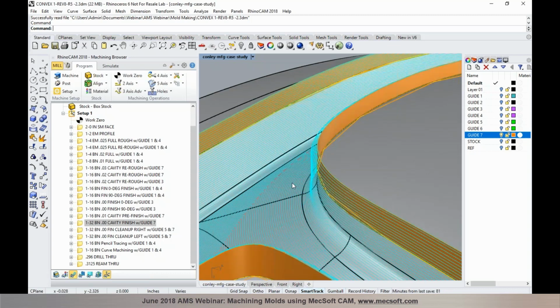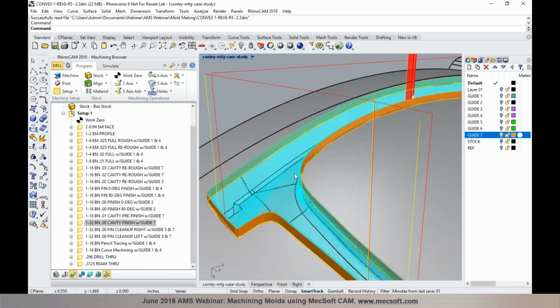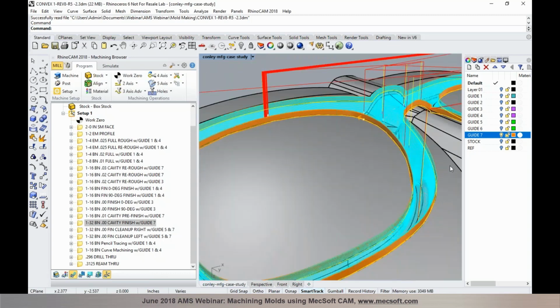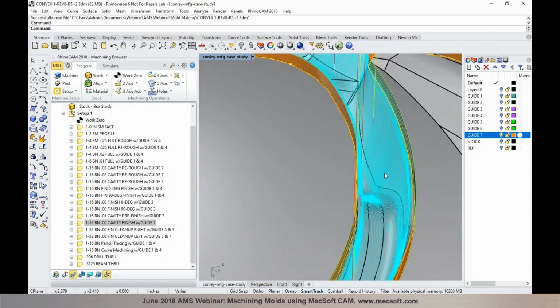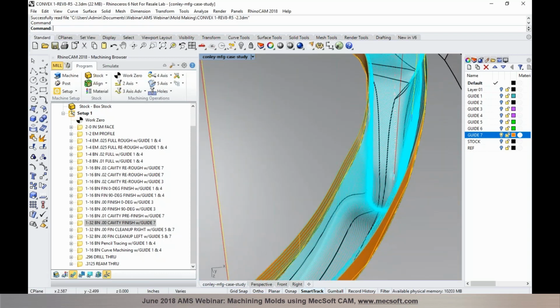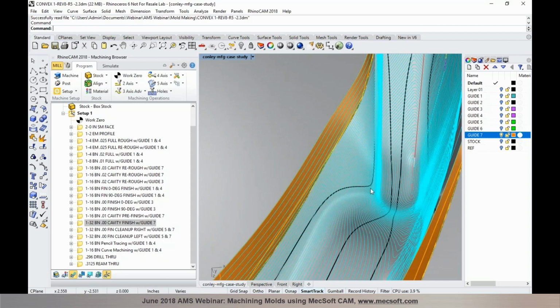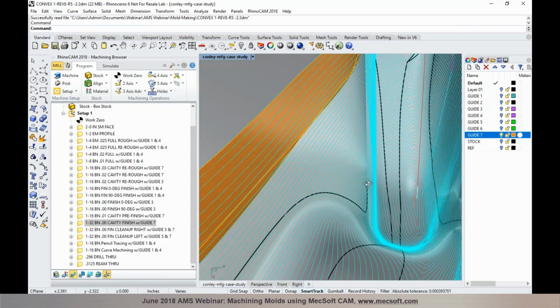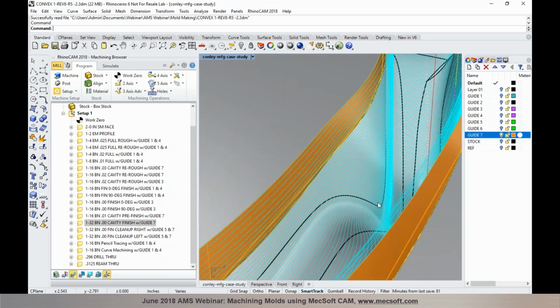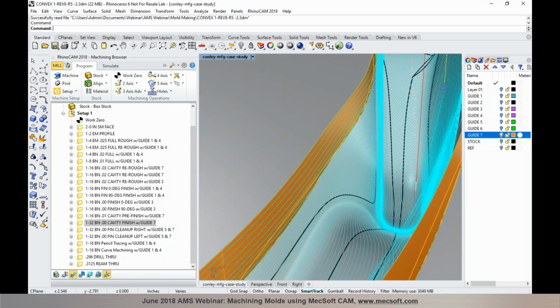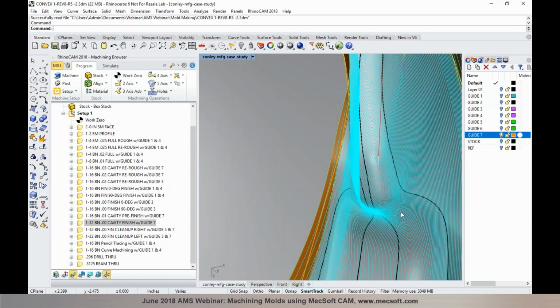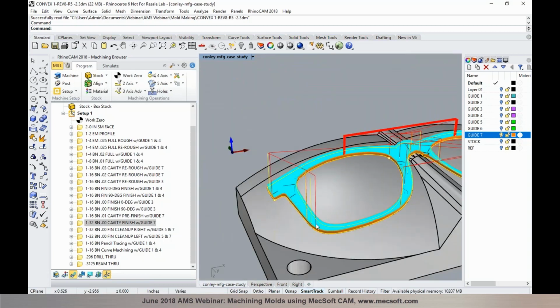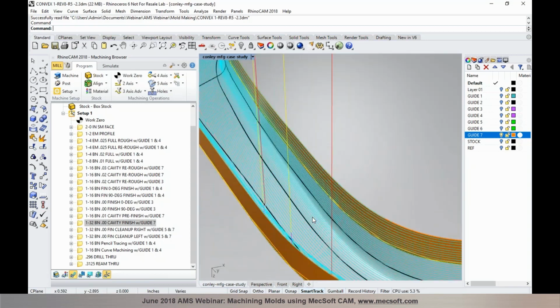So you can take advantage of some of these advanced 3-axis toolpath methods that are offered in our Pro and Premium configurations, and look at the nice transition of the toolpath, and it maintains a uniform 3D step over, and it works great when you have both cavity regions or when you have steep areas. So you could use the 3D offset pocketing to achieve really good finish on these cavity regions on a model.